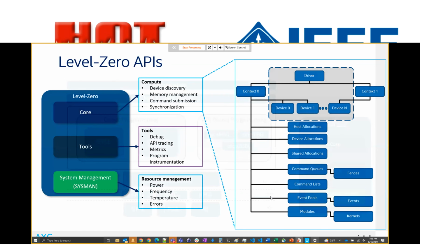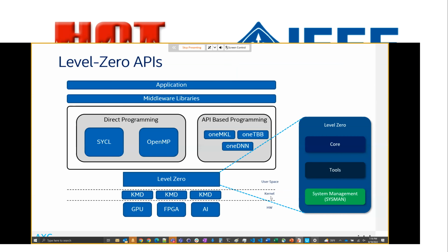And finally we have Sysman, which is the APIs to control the system and the GPU. We have APIs there to read and set the power, read and set the frequency, read the fabric and the topology, how the GPUs in your system are connected, etc. All those are part of the same level 0 specification. It's just subsets of APIs.